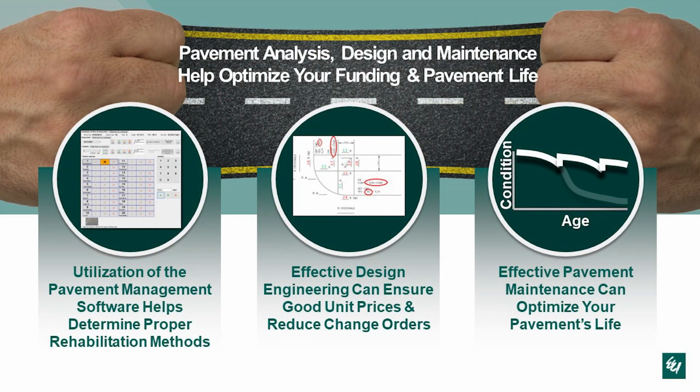So in conclusion, utilizing the pavement management software is the start of your CIP program, determining the proper rehabilitation methods. Are you going to resurface? Are you going to microsurface? Are you just going to mill off 2 and put back 2?